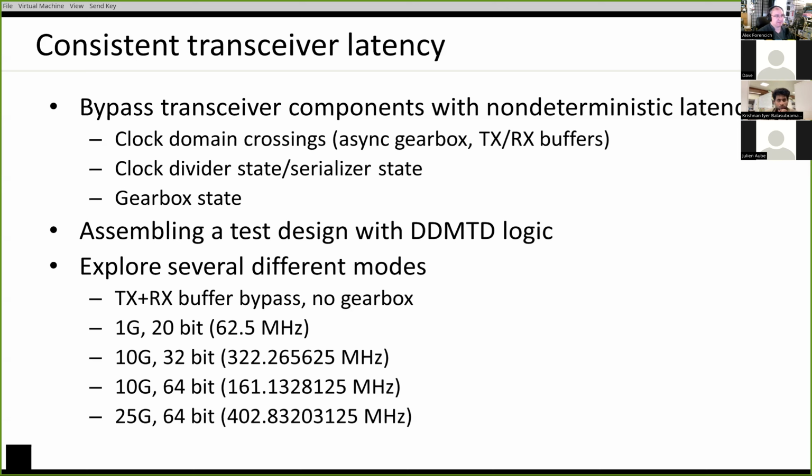And the basic idea that I've come up with is to send not exactly PRBS data, but something that looks kind of like the 64/66 encoding, where you have a fixed 0, 1, and then n-2 bits of PRBS. And then with that, you'll be able to see where the CDR locked, basically, right? Because for a 64-bit interface, you've got 64 potential barrel shifts that you could end up at.